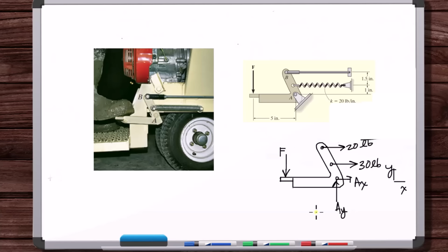And sometimes you need to consider the dynamic load cases. Sometimes the dynamic load case is what could cause something to break, right? What if somebody presses real hard on this and they keep releasing it and they don't release it slowly? Maybe that results in much higher pin forces than just the static fully pushed in case. You might have to look at that.